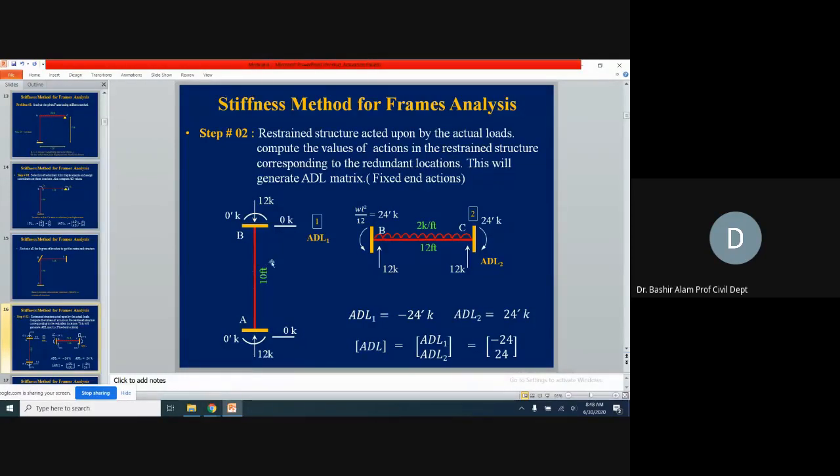So what happens now? The member end moment is equal to 0. Why? Moment is always load times distance. So if we don't have load, so it means we don't have any moment. There is no moment and there is no shear force also. Nothing is going to be balanced by these shear forces.